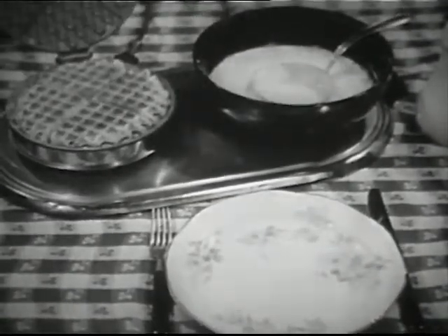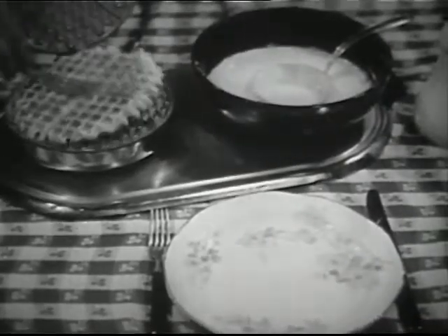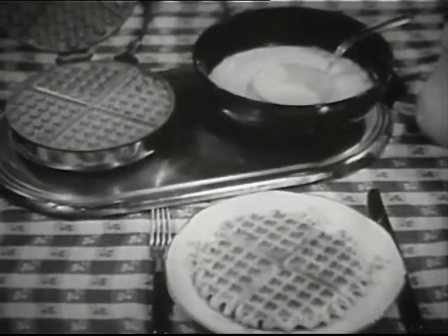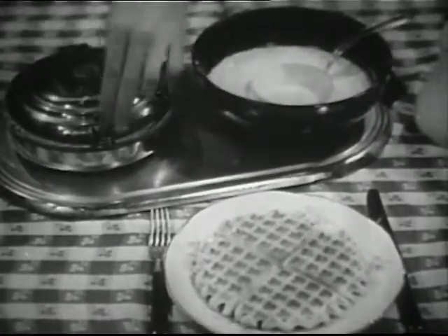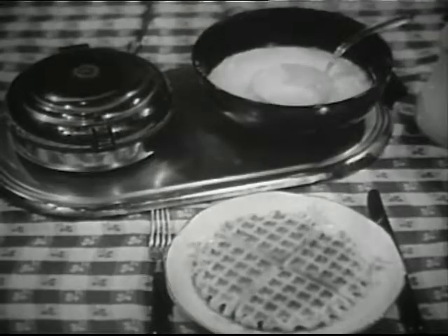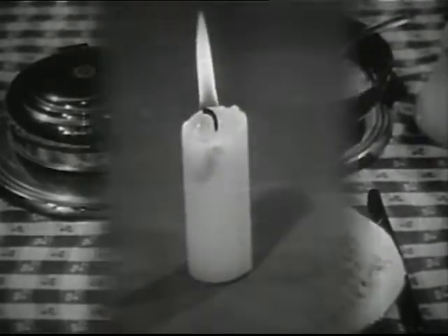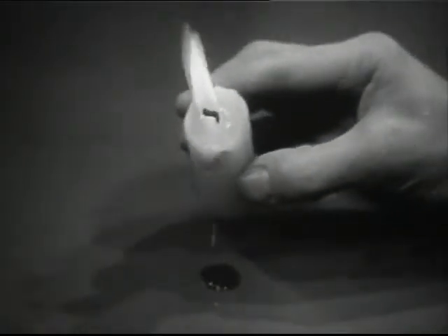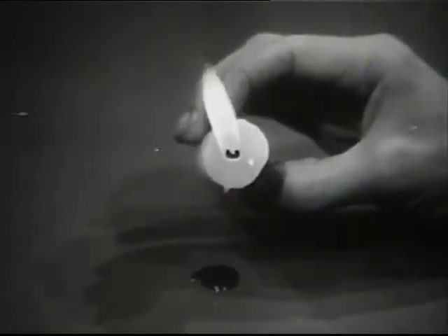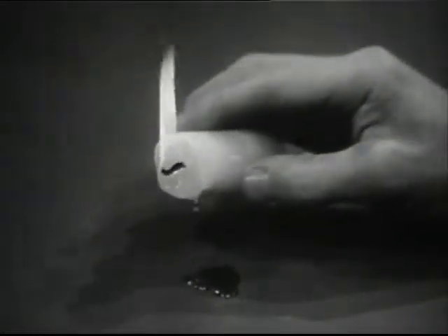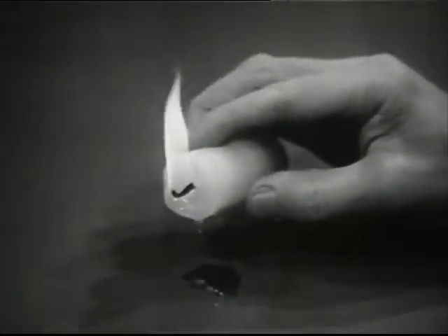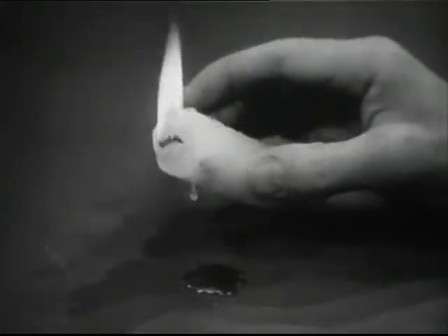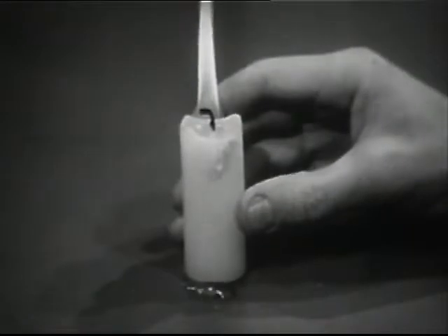Thermosetting materials are hardened by a process that can be compared to the making of a waffle, which once it is set under heat cannot be melted or reshaped. So we call them thermosetting or hot set materials. Thermoplastic materials can be compared to wax or paraffin, which hardens by cooling. They can be softened by heat and reshaped, and will then harden again by cooling. Thermoplastic materials are often called cold set compounds.